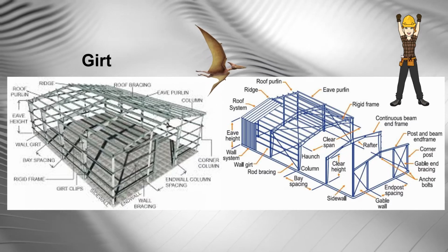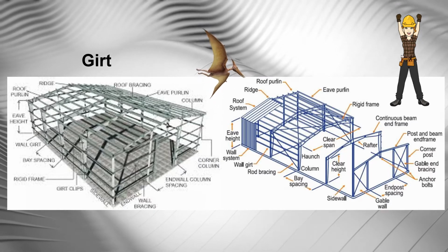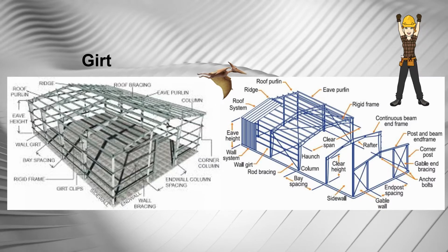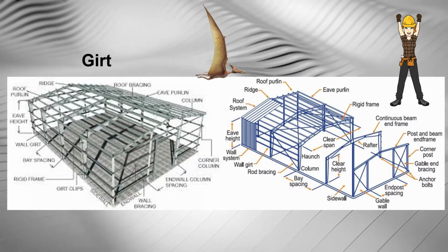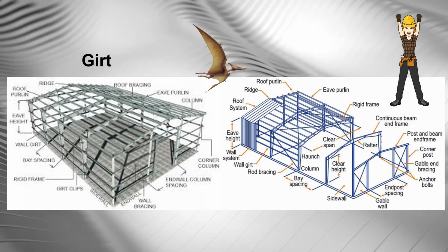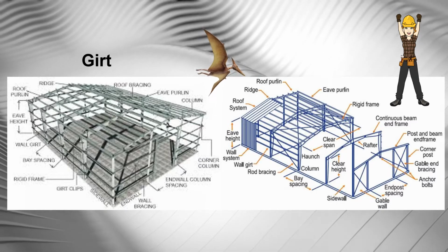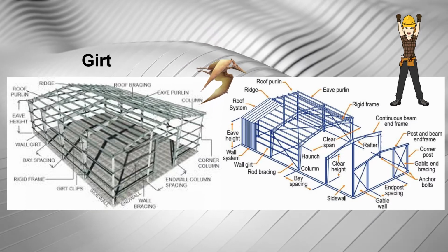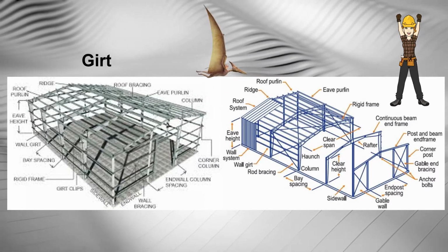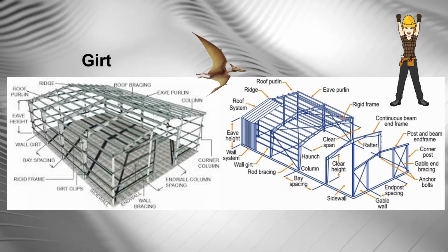Under restricted circumstances, sheet metal wall panels are also capable of providing rotational restraint to the girt section. In general, girt support panel, panel stabilized girt, column support girt, girt stabilized column.